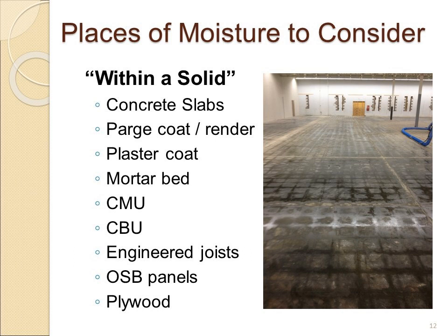If you have joists on a project, whether residential or commercial, and they're not protected, and they're subjected to water, rain, moisture, those engineered joists can lose their rigidity, lose their strength, and although you planned for those joists, or you were told those joists were going to meet a deflection rating of, say, L over 900 or 700 or what it might be, because they were affected by moisture, you could significantly drop the amount of deflection resistance down to a lower amount, and now your 24-inch on center framing in your floor is not going to meet the deflection ratings that are going to be acceptable for your tile.